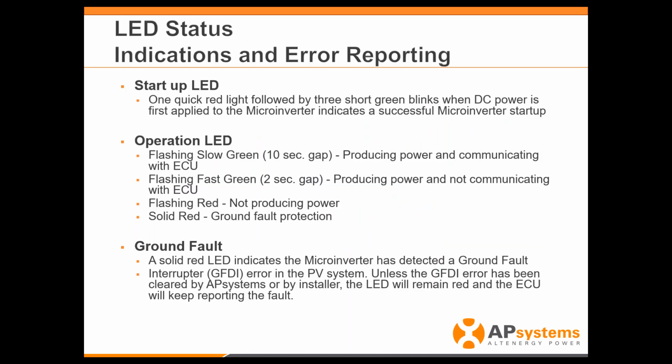As far as the troubleshooting is concerned, this is actually a really nice feature, and we just talked about this a moment ago. LED status, and like I said, I understand sometimes it's very difficult to see this under the panels as they're installed, but there's a few things that happen before the panels are actually installed. So the startup LED is a key one right here. When you plug in your first DC line, the first DC panel into the device, you're going to get 1 click red followed by 3 short green blinks. This is going to tell you that you've actually made a good DC connection.